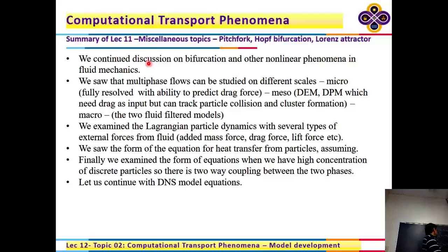It looks at residuals in the velocity field to decide when to terminate, and it just terminates. I even tried 10 to the power of 5 for the initial pressure, and still it is the same value everywhere. It's constant. I think that it's not an initial guess problem.